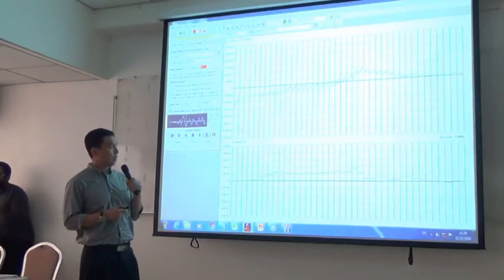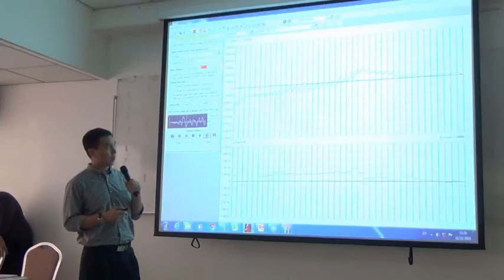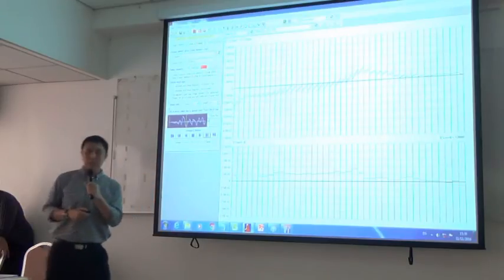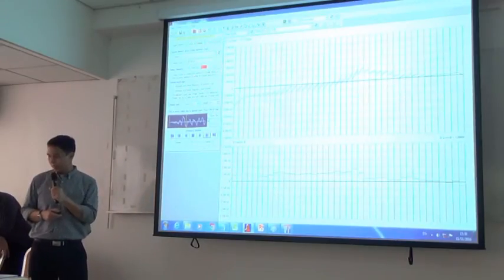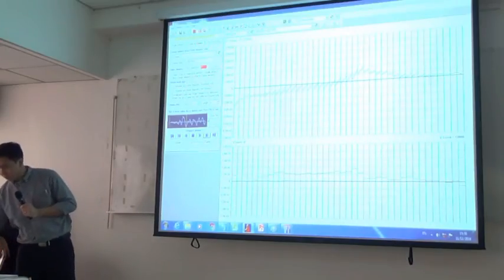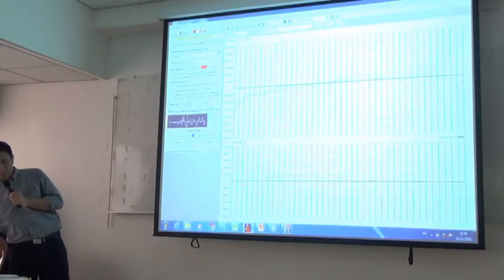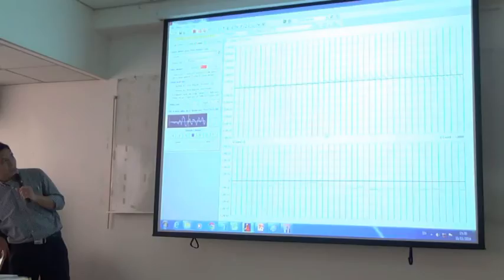As you can see here in the upper levels, in the moment diagram of those floors, it looks like the unsupported span is from here to here. There is no proper double curvature in these floors. As you can see, this looks to be due to the yielding of the girders which are connecting to them. Now we are passing the peak of the ground motion, so the girders are also highly yielded, and we are getting large demands.